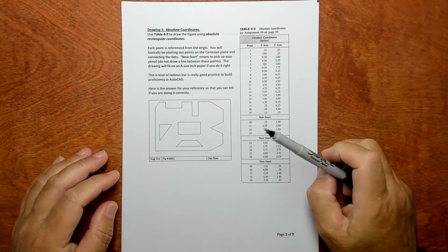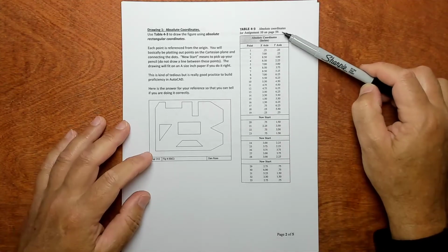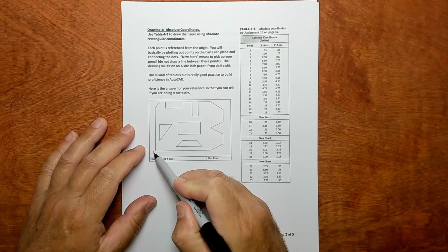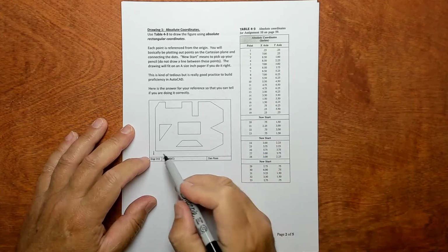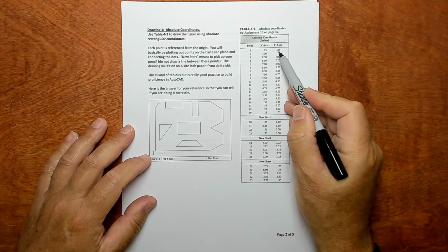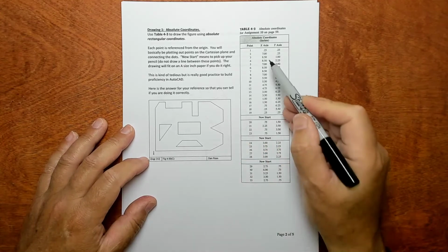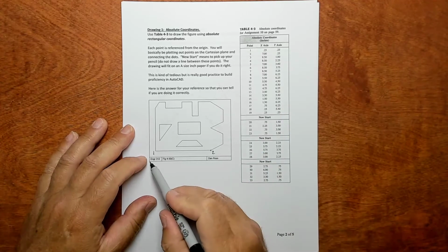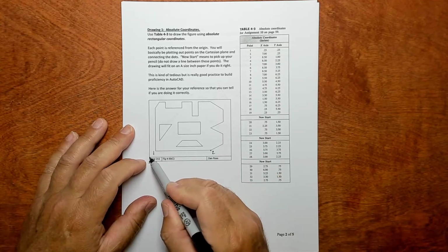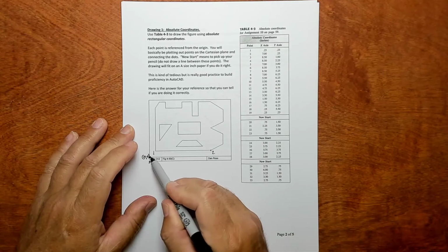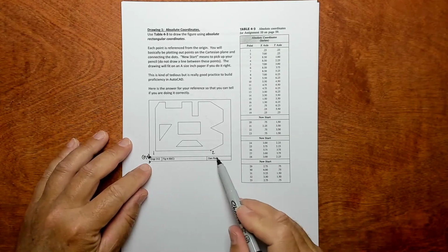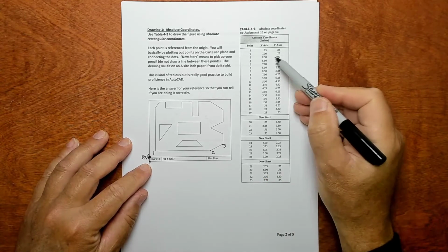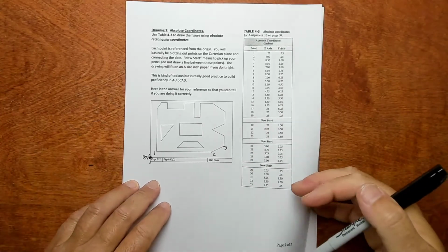All right, so here's the first drawing. It's this thing. So it's a bunch of absolute coordinates. You're just plotting, like this point here. This is point 1, and it's at absolute 0.25, 0.25. Like it's 0.25 over and 0.25 up. Okay, point 2. This is point 2. It's absolute 7, 0.25. So it's from 0, 0. Let's say 0, 0 was here. Okay, then it's 7 over and 0.25 up. Okay, this point here is 3. It's 8.5 over and 1 up. Okay, that's absolute. I'll do this in AutoCAD for you.